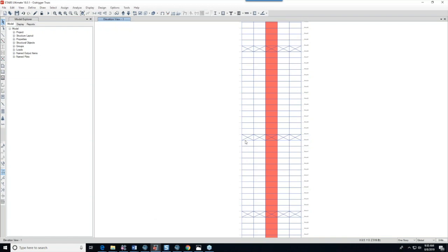And if they are, of course, that's why the joints along the top and bottom chords of the truss would be restrained by the rigid diaphragm. Those joints would not be able to move relative to one another, and therefore they will not be able to load the top and bottom chords if you have a rigid diaphragm.